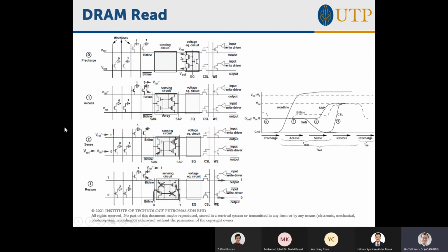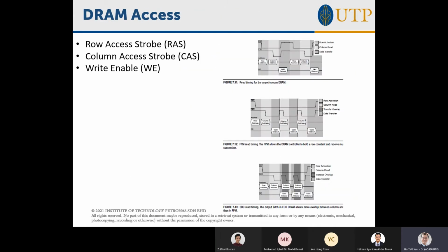So that's why you always have to select the row first, which is selecting which of these bits to update the bit line. Then you give it some time for the access, sense, and restore to happen. Then you go and select which of these bit lines, the column access, you want to select. That's why the row and the column accesses are one after another. And after that, only then do you have your data that is valid out here.